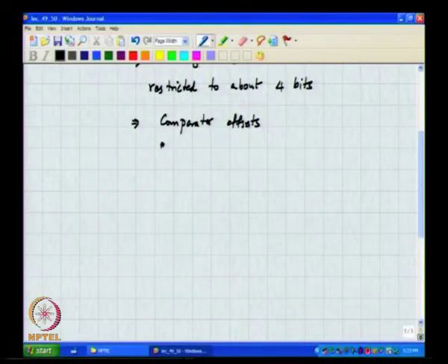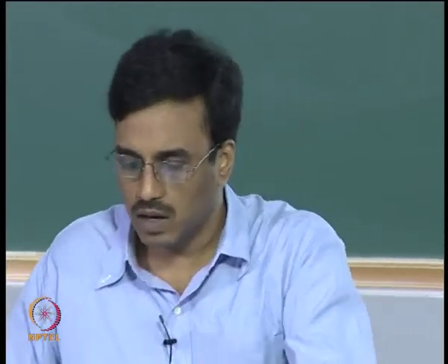Now, the only thing that one needs to worry about typically is to make sure that the characteristic does not become non-monotonic, okay, and which can become a problem when the converter is embedded in a feedback loop.